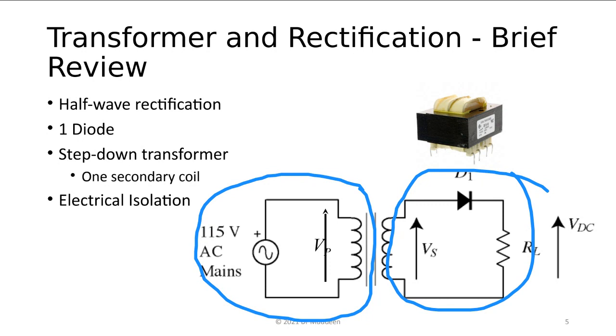So once you make sure that on the secondary side at no point do you have any of the wires coming back to the primary side, attaching to your live or your neutral, then you are electrically safe. There's no way you can get line voltages appearing here. So a good advantage of a transformer is that it gives you electrical isolation.